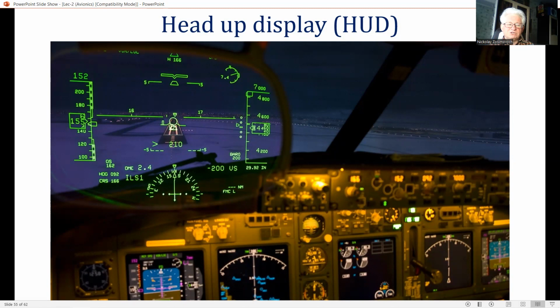This figure shows a civil HUD installation. The HUD elements are precisely located in a rigid mounting tray, which provides the necessary mechanical stability, and the combiner can fold out of the way when not required. The field of view is 30 degrees by 25 degrees.